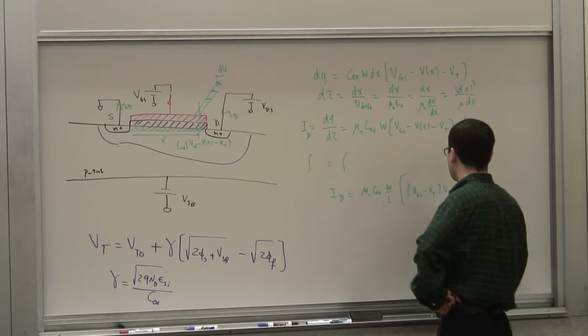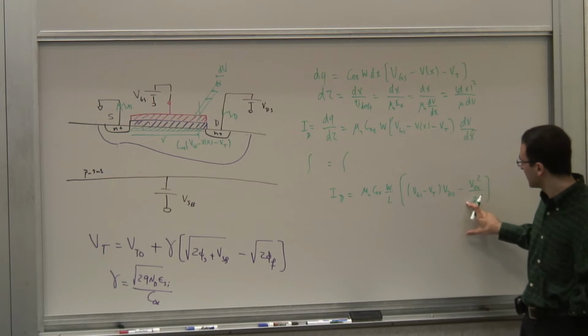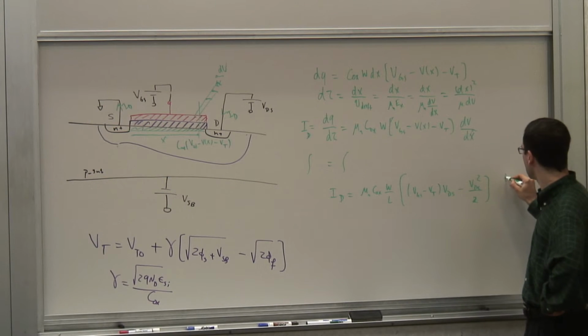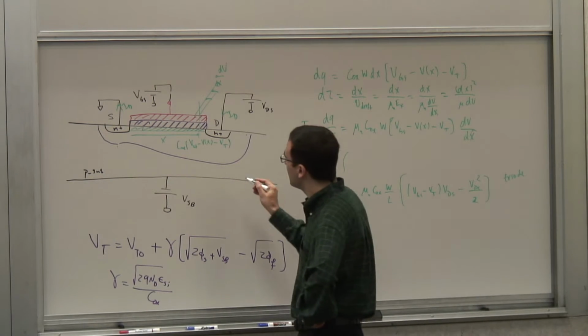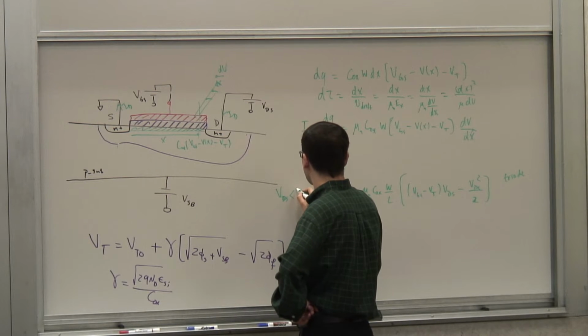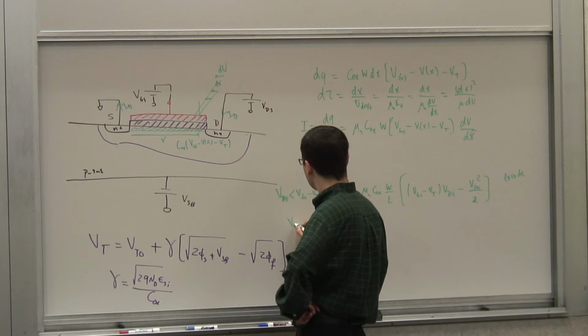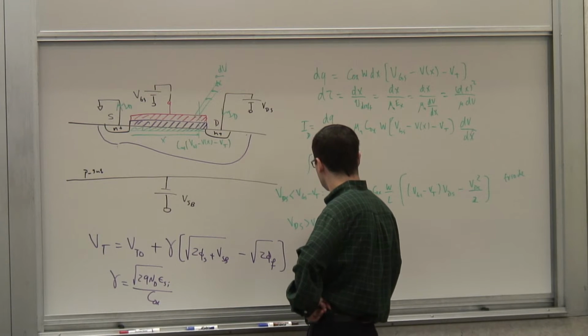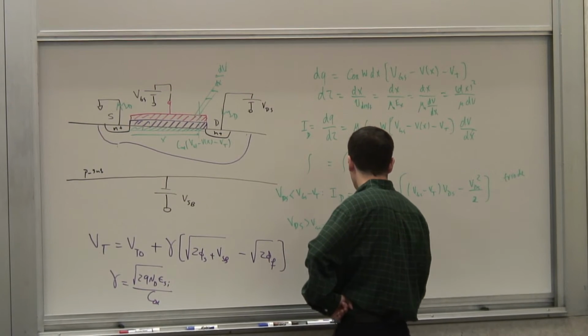So we had this linear region, the linear part, which was a voltage controlled linear resistor, and there was a correction term. And this was basically associated with the triode region. And then we saw that this is for VDS smaller than VGS minus VT. And then when it became greater than that, our expression for the current became what?